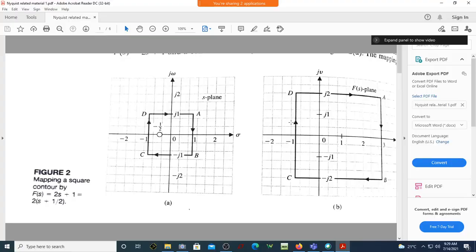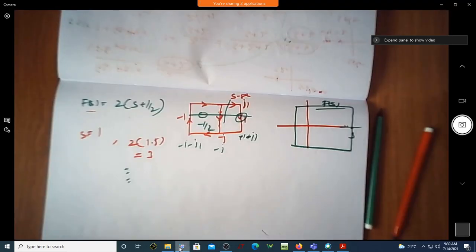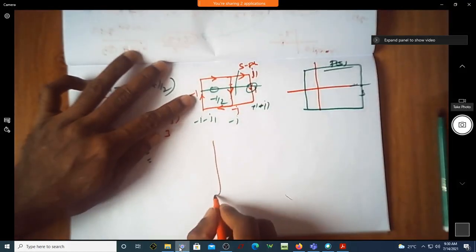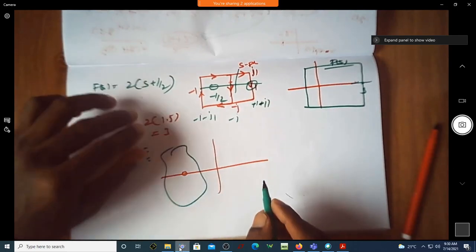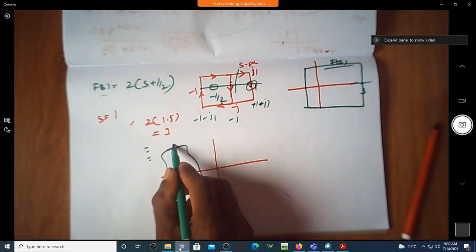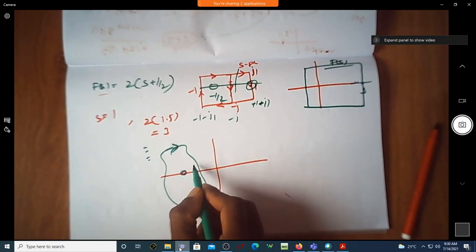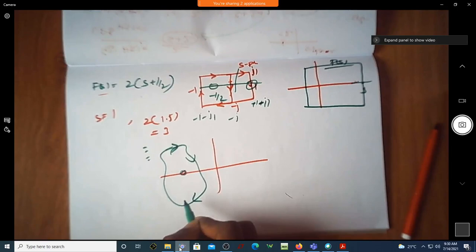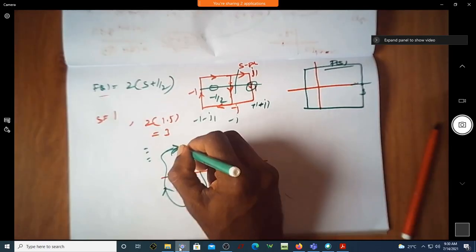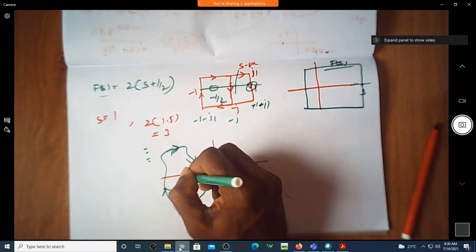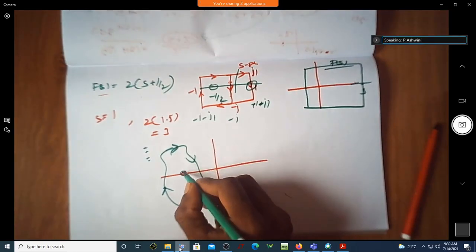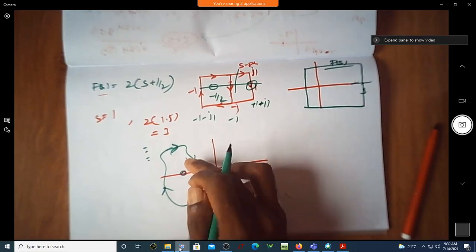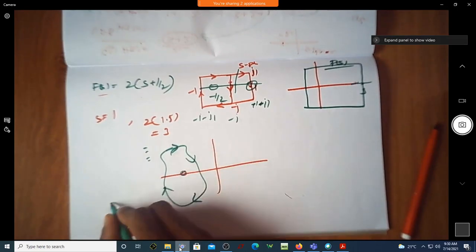If you see this contour, now we will define two things. One is called enclosure. You have a contour, assume that you have a 0 here. I'll write a random contour. When I write a random contour, can you see, is this 0 coming to the right of this direction? Assume that you're traveling here. So where is this 0 seen? Is it towards right or towards left? Is it not towards right? So if there is a 0 towards the right of this contour, I'll call it as enclosed.